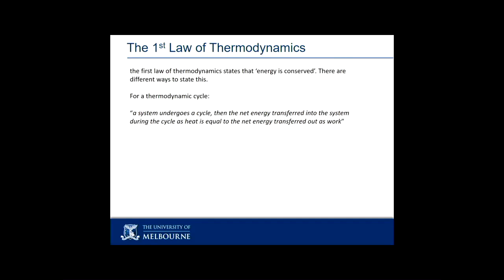Also, I put some heat in, some of it came out again. So the net heat transfer, not the heat I put in, but the net heat transfer. I probably lost some heat as well. In my piston cylinder that had some combustion in there, I released a whole bunch of chemical energy as heat. But I also have this really hot car engine with oil flowing through it to keep it cool. I am taking heat out of it all the time. So it's the net heat transfer into the system needed to come out again because I came back to the same point, the same energy state.